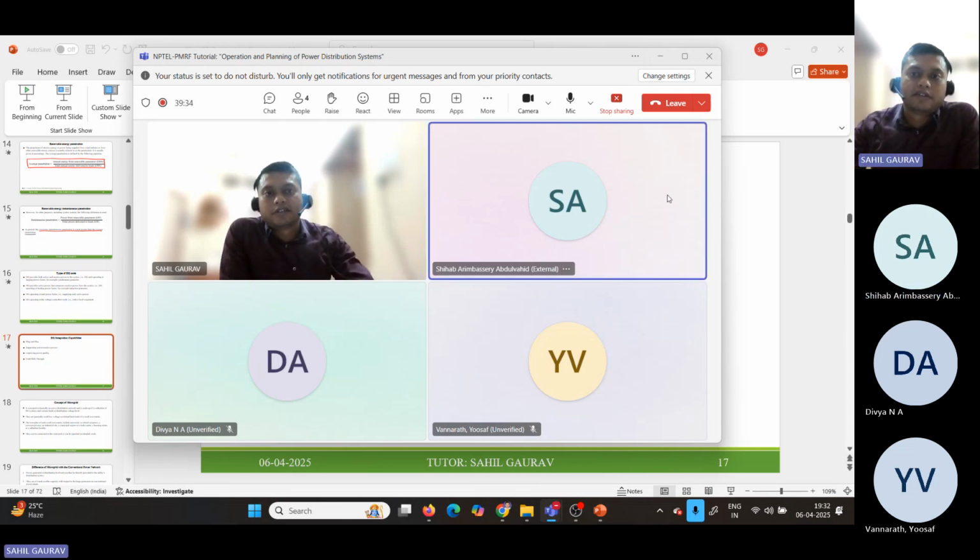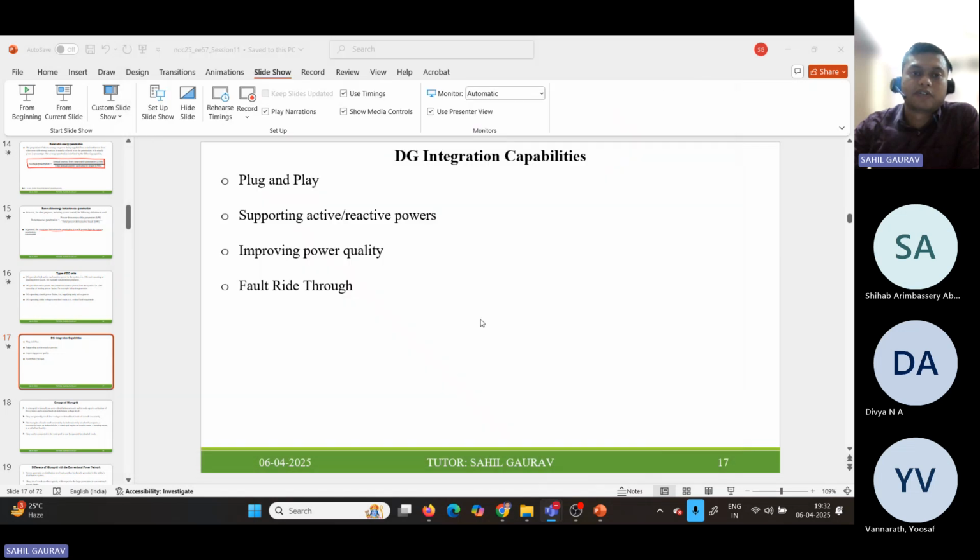Generally, whatever I know, we have low voltage fault ride through or high voltage fault ride through, meaning your system should not go into instability when there is some rise in voltage at the node or some drop in the voltage level. I don't think it is related with short circuit condition or open circuit condition. For short circuit, I think we should refer to some paper if you want a detailed discussion about fault ride through.